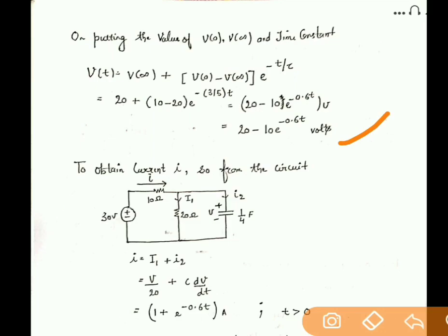Now one very important thing in this particular capacitor voltage is that the capacitor voltage waveform is continuous, because once you put the value t equals 0 over here, the waveform will certainly not switch instantaneously, it will be in a continuous mode, from t less than 0 to t equals 0 and t greater than 0.